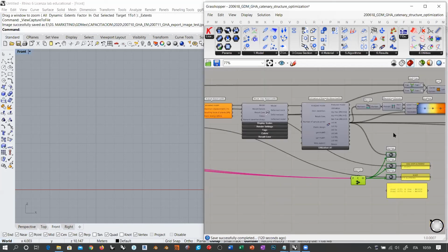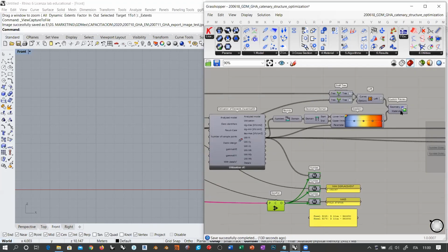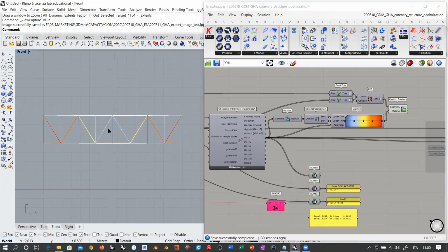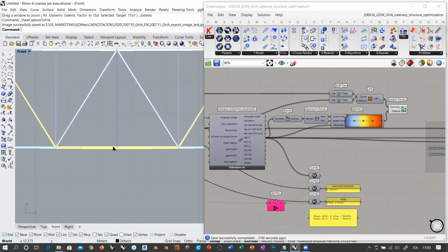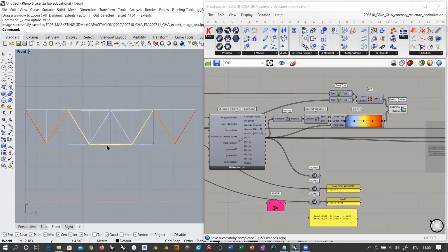Or whatever type of consequences I want to implement in my system. And I am also visualizing this. Okay, so actually these colors here, I was wrong. They are not representing the displacement. They are representing the usage, the utilization of the elements, and of course the shape here is the actual displacement of the deformed system. But the colors do not correspond to the displacement. So this is the usage. The more used elements are the reddish ones. The white ones are basically not used in terms of normal stresses. So this is the information that we get from this graphic.